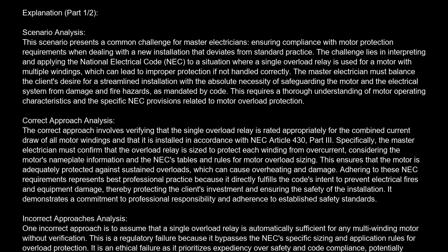Explanation. Scenario analysis. This scenario presents a common challenge for master electricians, ensuring compliance with motor protection requirements when dealing with a new installation that deviates from standard practice. The challenge lies in interpreting and applying the National Electrical Code, NEC, to a situation where a single overload relay is used for a motor with multiple windings, which can lead to improper protection if not handled correctly.